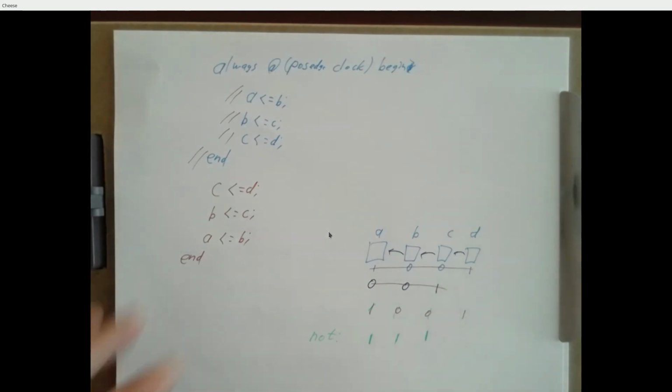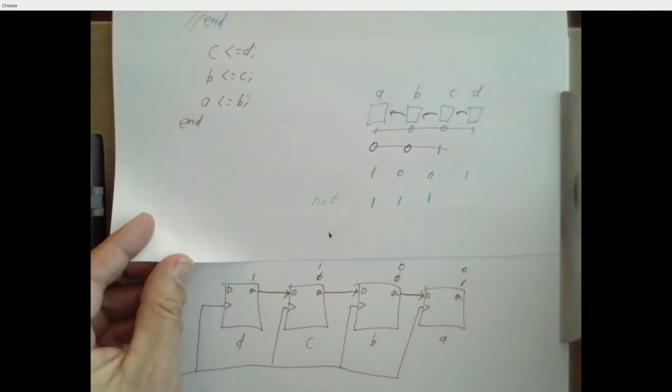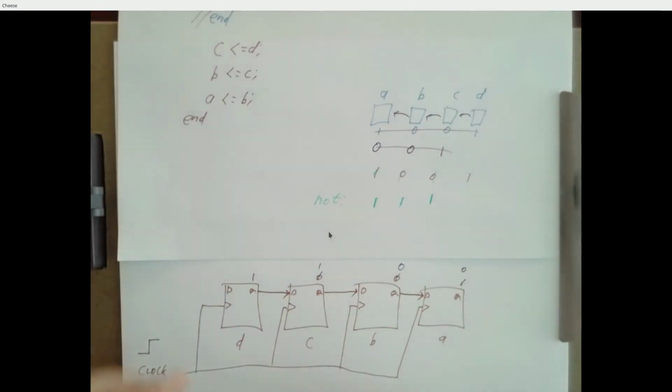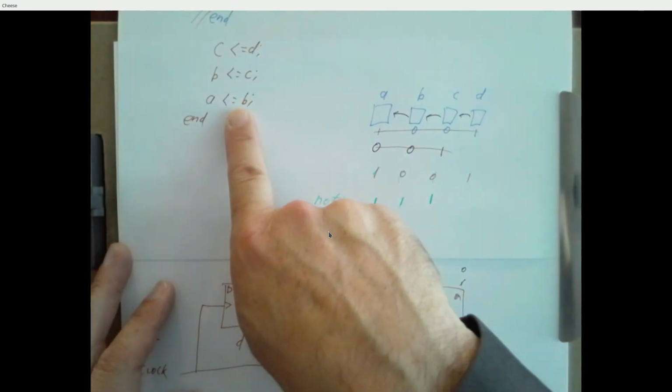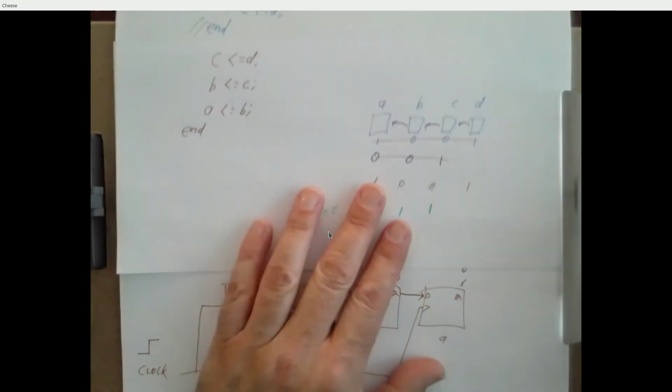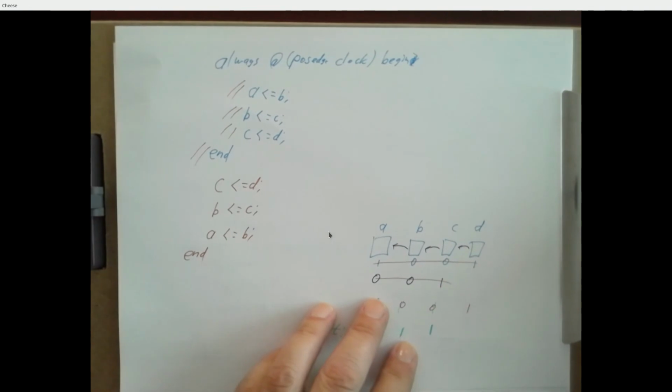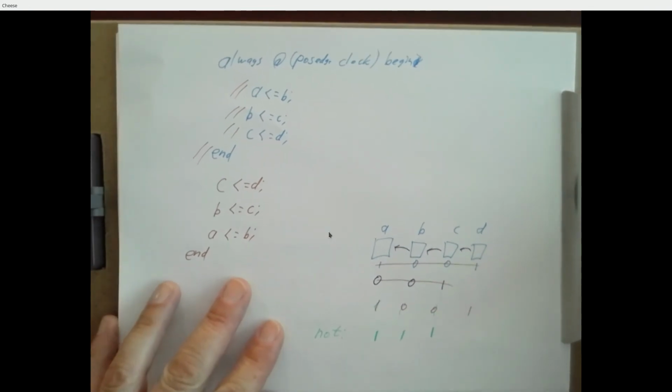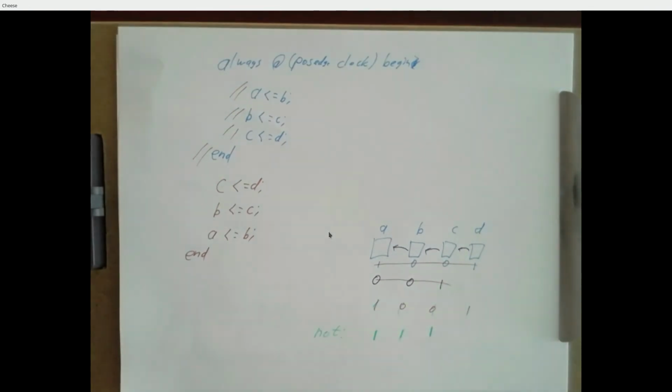All right, so one of the take-homes from this: it's useful sometimes to think back to what your synthesized hardware looks like. You write this and it's not doing exactly what you thought it would do. Think about what the compiler is going to do. What kind of hardware is it going to build? And this is where I need to introduce some forbidden knowledge. And it's forbidden because once I introduce it, it may be misused.